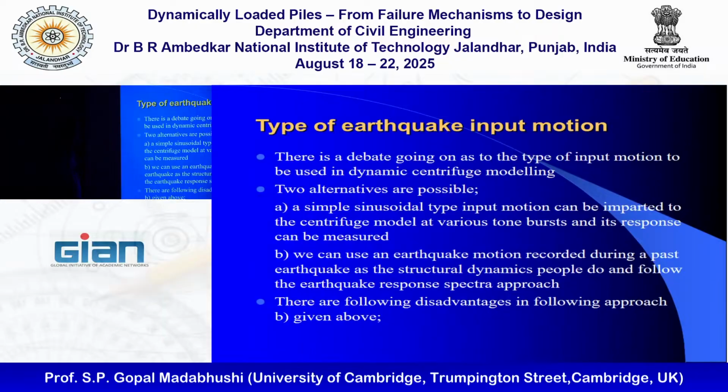There is another alternative, which is to use the simple sinusoidal motions. And my professor Andrew Schofield always said we learn more from sinusoidal motion. The reason is when you are applying sinusoidal input motion, it is very clean input. There is one frequency and an amplitude. So you can then see what the soil and the structure are doing in response to that shaking.